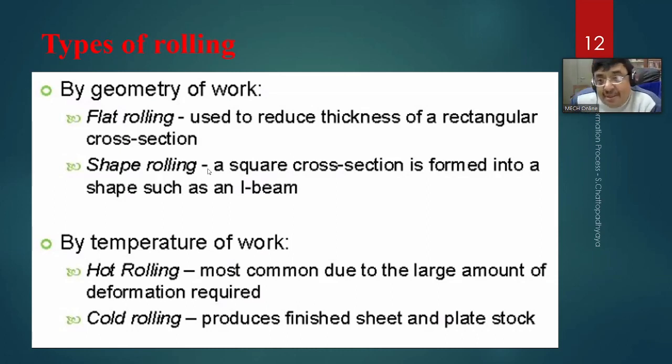Weldability is crucial because you have to deal with many thicknesses, and according to that you do. Whenever the carbon content is less, that is why it is called mild steel, the manufacturability will be high. Whenever the carbon content becomes high, the machining capability will be less. Is it clear, students? Cast iron has a higher percentage of carbon. Carbon is acting as a molecular reinforcing agent. And it is true not only for metal, it is also true for rubber. I know that because my first industry was a rubber industry.